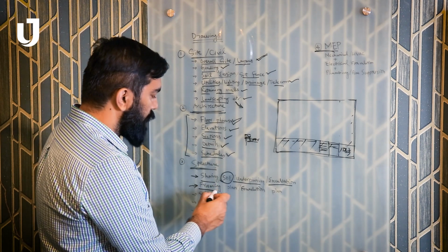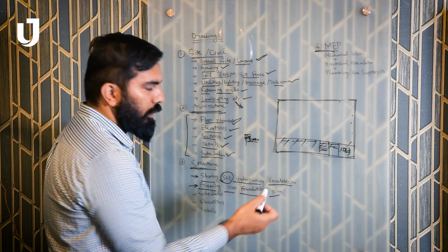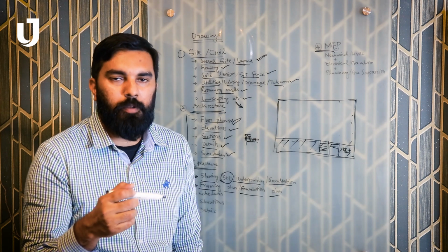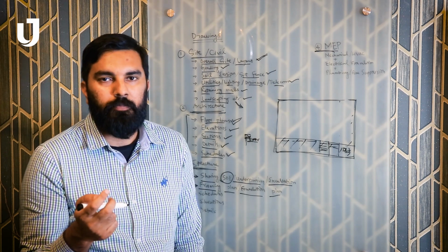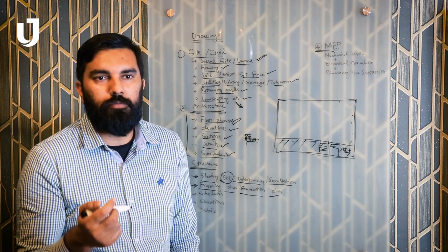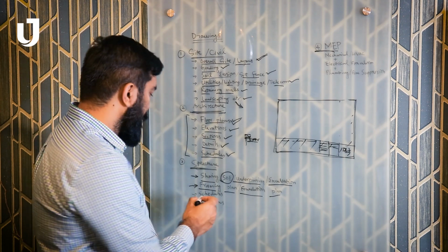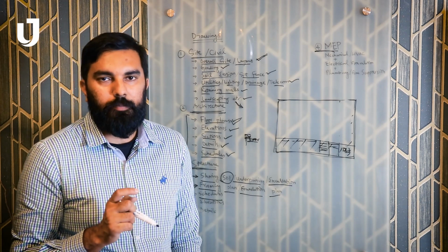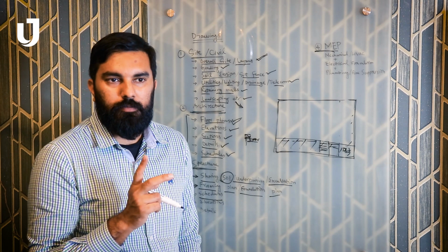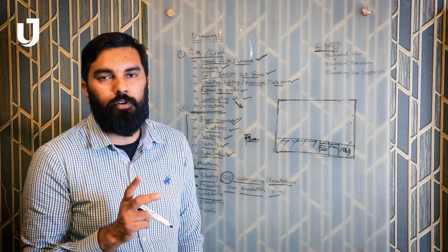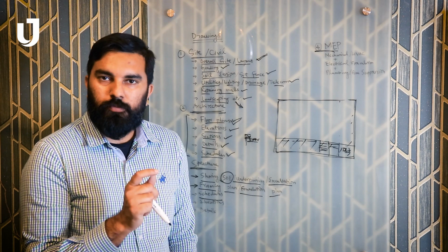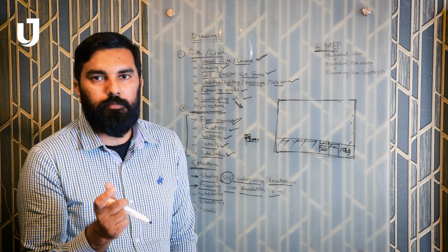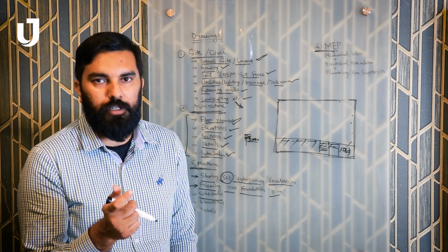After shoring, we have the framing plans, just like I told you, foundation plan. Then afterward, for every floor plan, we'll be having a framing plan where we have beams, the columns, the metal deck that you're going to use, metal deck or any other deck. Then we have the schedules. In the schedule portion, sometimes the beams and columns can be presented in the form of schedules. Which column type, which beam type, what's the reinforcement, what's the steel beam size or steel section sizes.